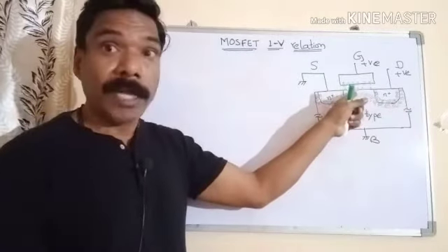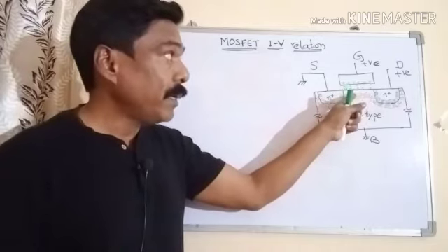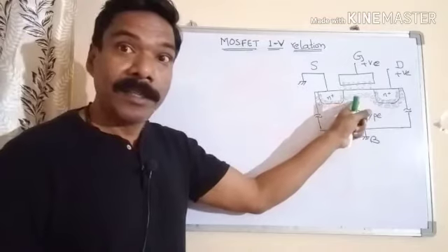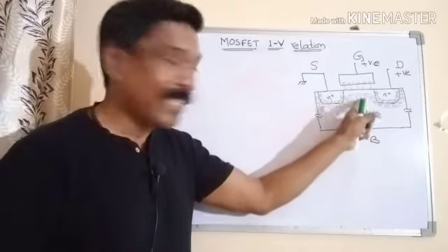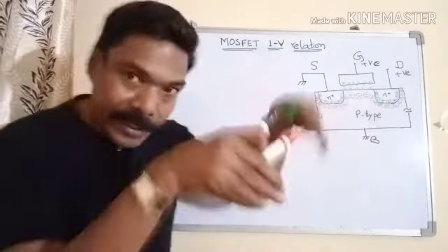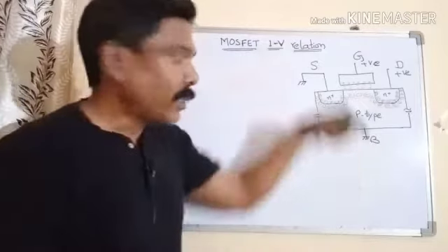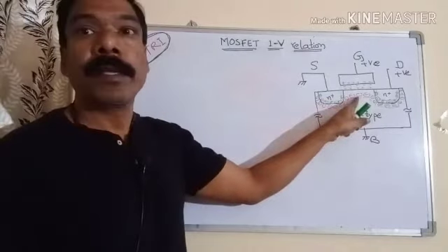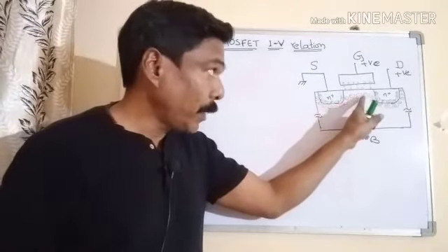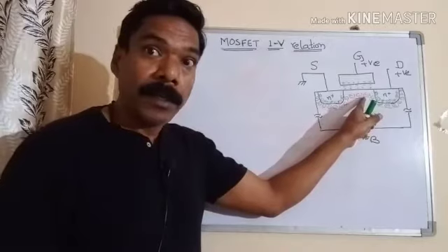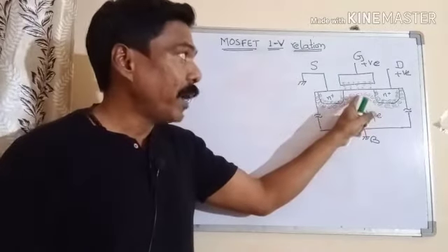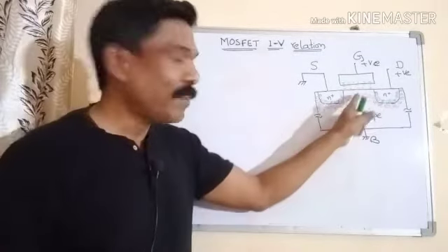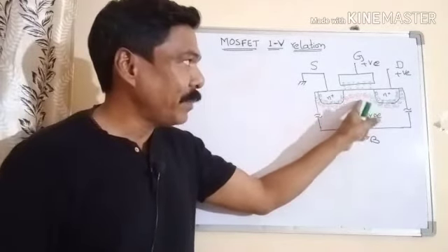So that positive charge at the bottom of the dielectric layer is repelling the mobile positive carriers in the background silicon, that is the body. That means the holes are getting repelled, going down, and they are called depleted. When the holes are leaving the atoms there, what will be left behind? We are left behind with negative immobile ionic charges. That is the depletion charge. So negative charge is there in the P-type semiconductor.